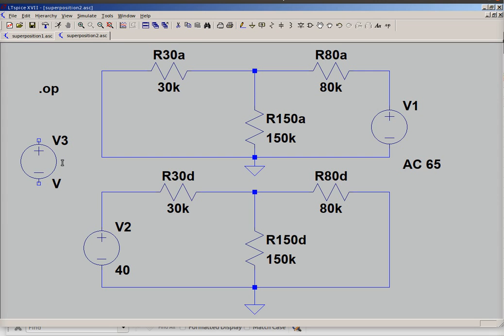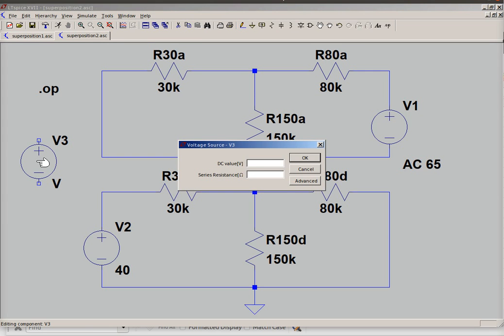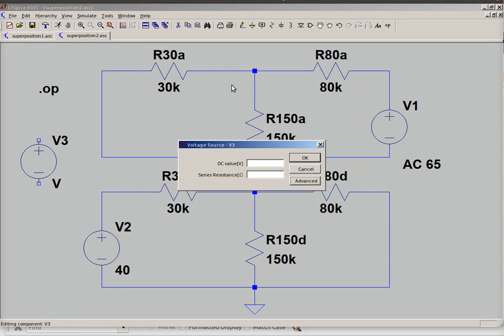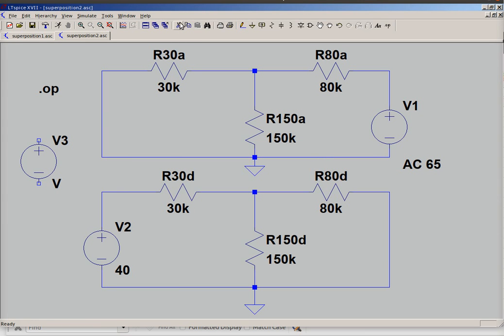And just a random voltage source, and then to set the value AC, what I did is I right mouse clicked on it, went to advanced, and then I put in the RMS value where it says amplitude. Purists will have a problem with that, but for our purposes, if we start out with a voltage that we consider RMS, the values that it gives us for current and everything will be in RMS. So it stays apples for apples, if you will. So I'm going to cancel that and cancel that, and then get rid of that component. That's how I set the voltages.